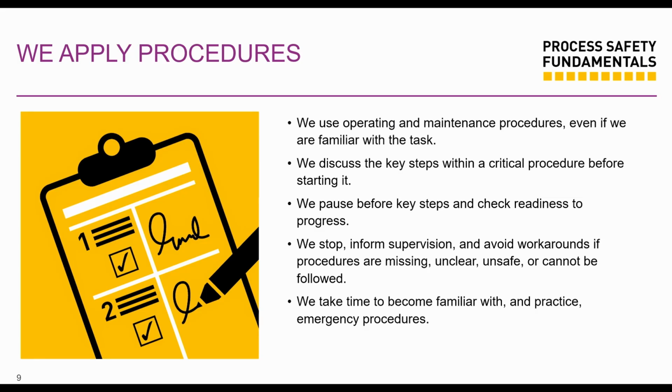And you come in saying, oh, this is the usual day-to-day task, let me just run it normally. And you're not aware that stuff has changed. So when stuff changes in the plant, it's part of the MOC process to capture that you need to update the procedure. So always make sure you have your procedures on lockdown, that you have them, you know them, and you're following them step by step when you're carrying out a task.